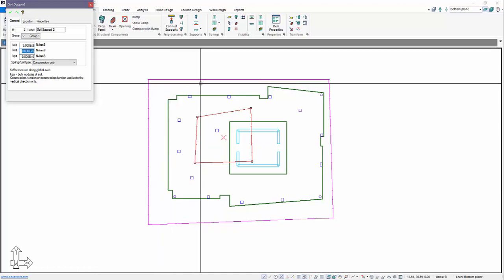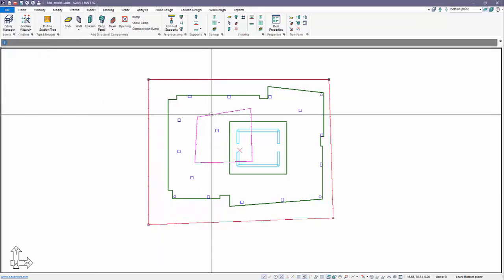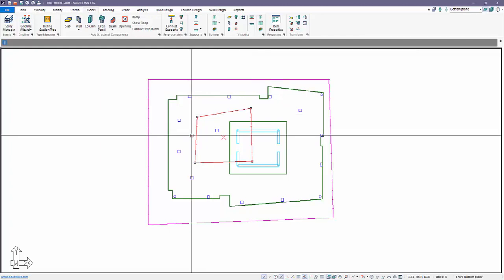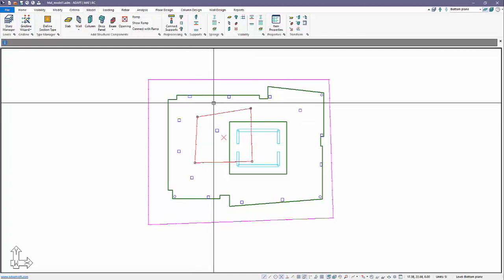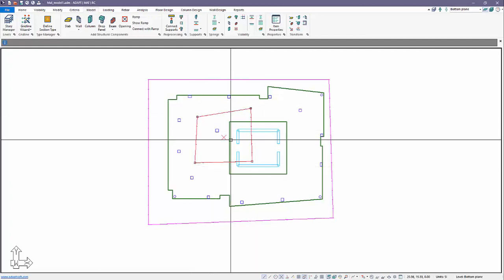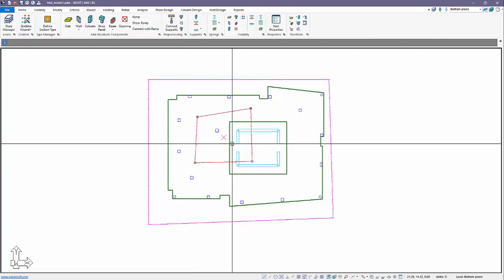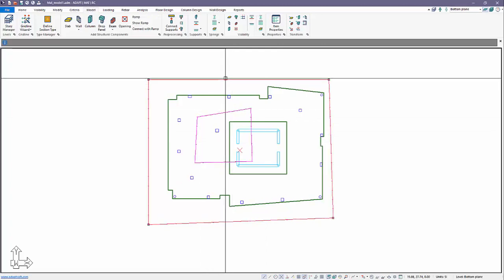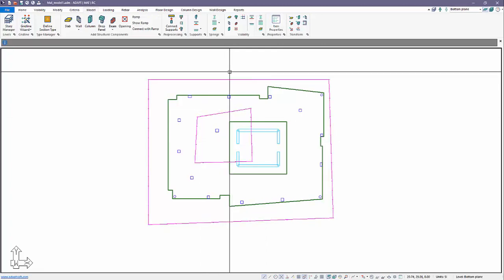Okay, so now we have springs that are overlapped. This spring is on top of this one. The program will conservatively take the lower value for the spring assignments that are overlapped. If the user wishes to have this region be 5 E -2 and this be 2.7 E -2, then you have to adjoin the springs and not overlap them.